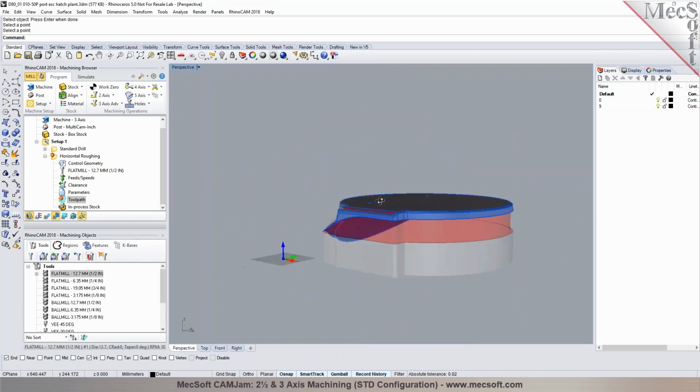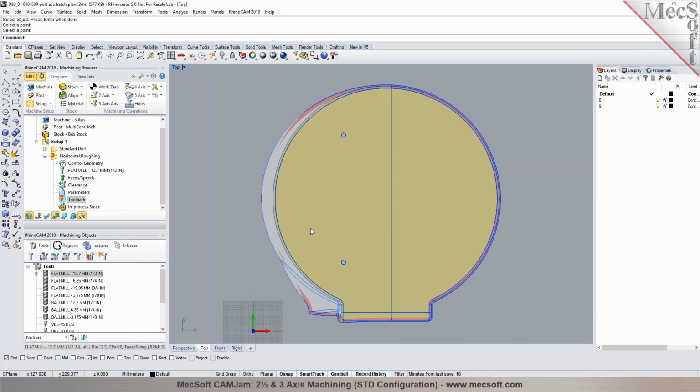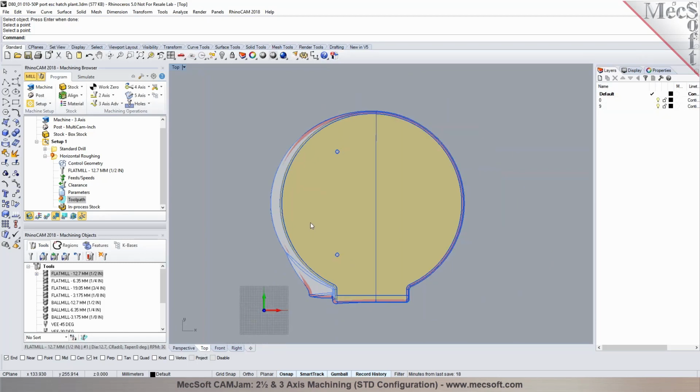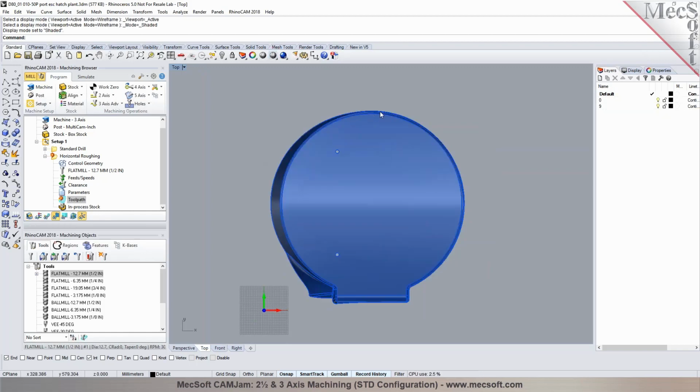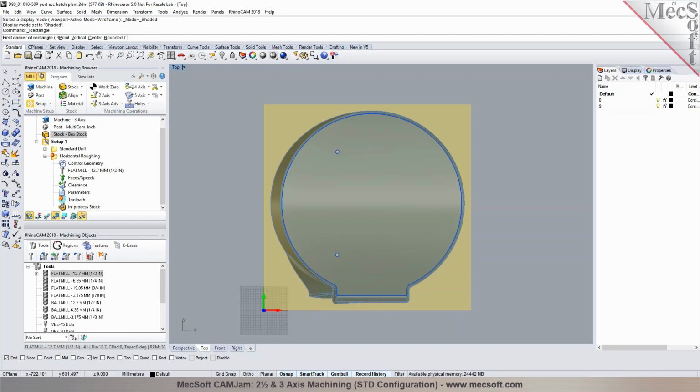While cutting it. So one of the things you could do is define a boundary in here and tell it how much of area you want to cut, rather than having to machine all the areas in here. So your boundary could be as simple as defining a rectangle, or it could be even a complex geometry in here, any complex curve. So in this particular case, I could say I just want to throw in a rectangle in here, and I can specify to just go right up to maybe a midpoint in here,